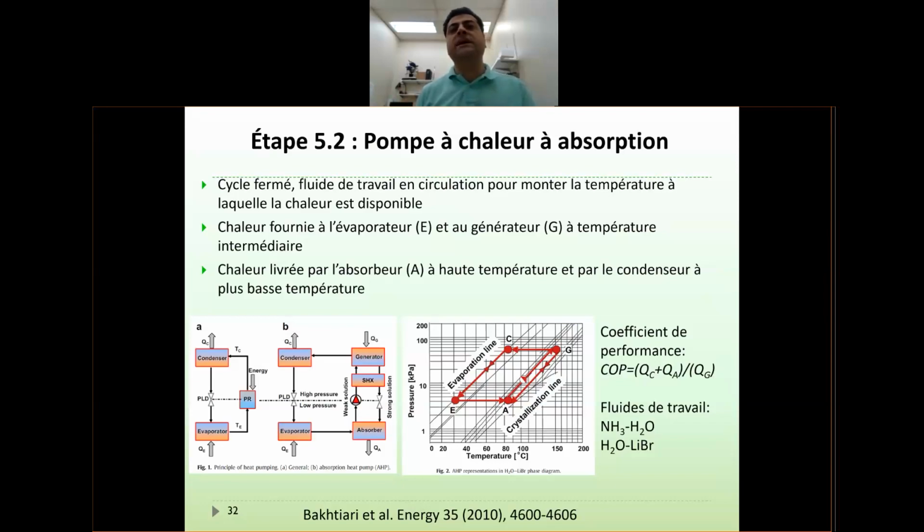We cannot just say I use a heater to increase the temperature. Okay, you use a heater. What is that heater? Does the heater use steam? Okay, if it uses steam, what steam? Low pressure steam, high pressure steam, medium pressure steam, or maybe the heater doesn't use steam. It just uses electricity, an electrical heater. You need to consider that.